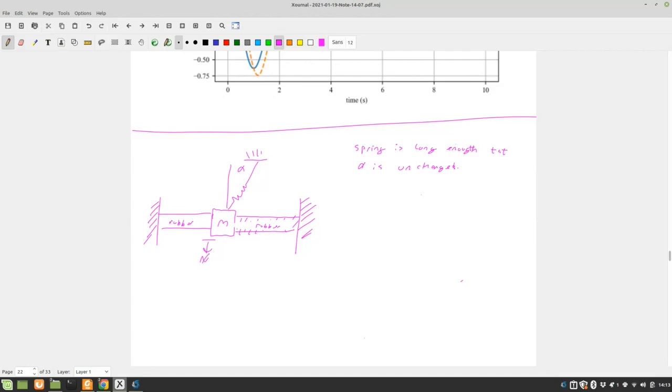So if our spring is at an angle, and our dampers don't add any stiffness, that becomes something that we can start to solve for. What is our first step? If we want to solve for the natural frequency of this, what's our first step going to be? Get our equation of motion. Yeah, but even before that, we want to draw out a free body diagram. It's a good way to solve all of life's problems.